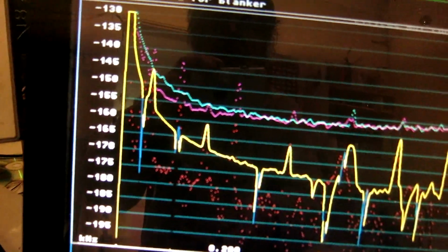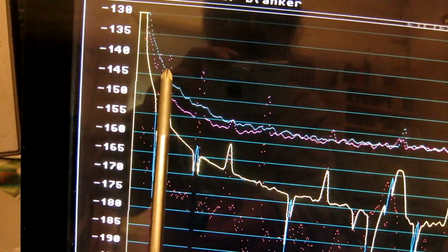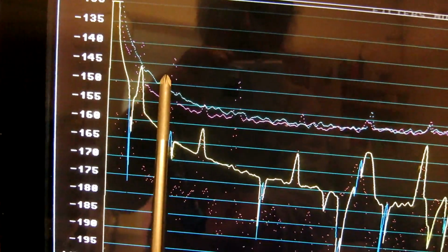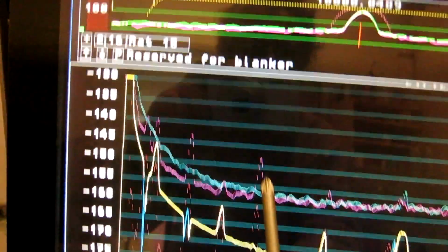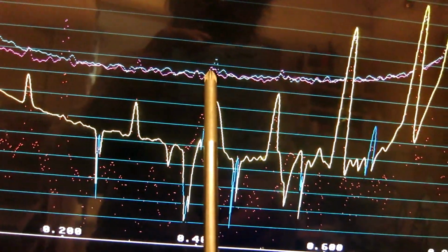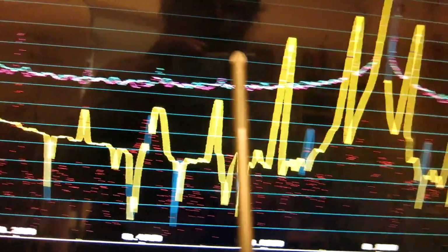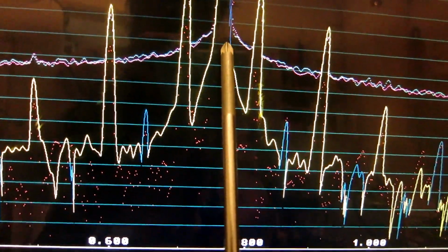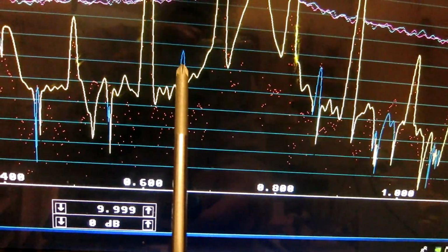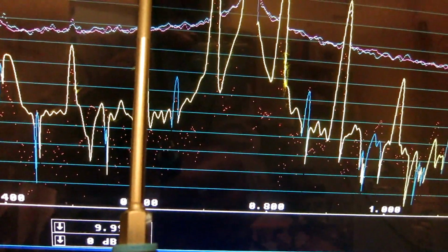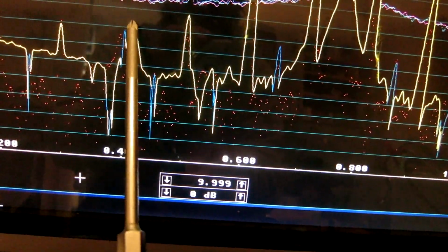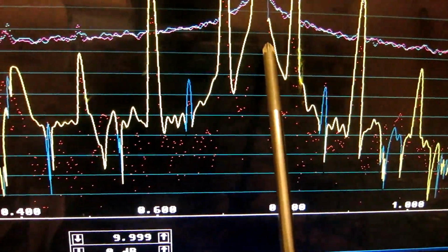There are many spurs. You can see in the power spectrum the red peaks, that's channel 2, 50 Hertz, 100 Hertz, 150, 200, 300, 400. And here you can see there are 2 peaks, because here is DC and 50 Hertz on both sides, 100 Hertz, 150, 250, 350 offset from the center.